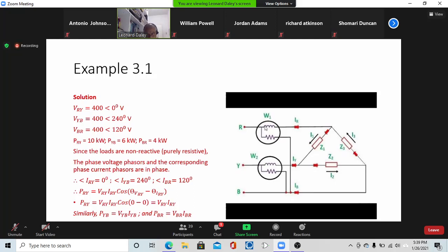So remember, R is considered to be at the higher polarity, and the common point would be at the lower polarity. So positive up here, negative down here. So we need VRB. So that's for watt meter 1. We need IR and VRB. So these are things that we are keeping in our mind, things that we need to find.